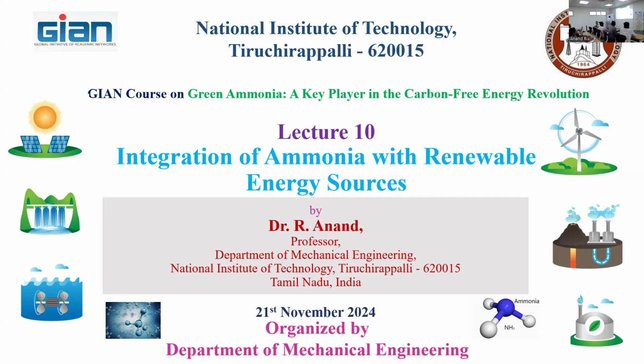So we need a work producing device called a turbine. A turbine is an expansion device where you can reduce the pressure from high pressure to low pressure. So we need to ensure that the organic fluid enters at some desired pressure. So you are going to produce the work output. If you connect the turbine shaft with the generator shaft, you are going to convert it into electricity.